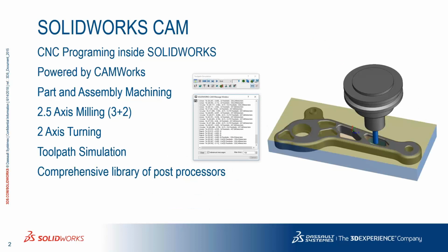It also comes with a toolpath simulation package, so anything you program, you will be able to simulate to make sure that you get the material removal you're interested in, and also that you avoid collisions with your fixture components. We also have a library of post-processors with the program, and it also comes with a development tool for those of you inclined to make your own post-processors.